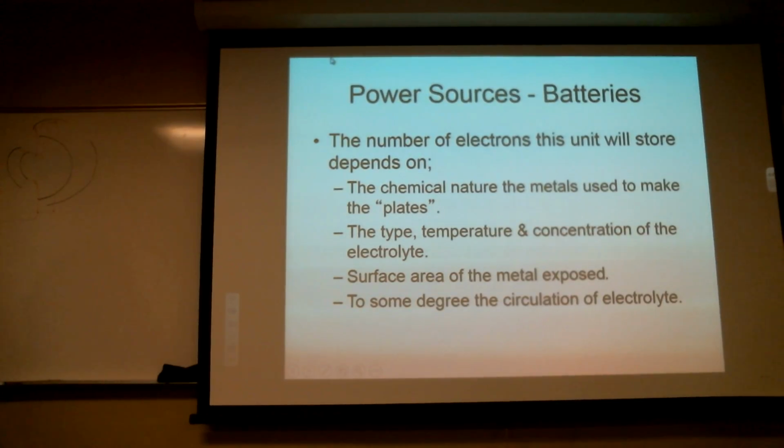Now, it's also important to note that in the world of electrical, we tend to do things in a manner of what we call preferred status. So the preferred values of voltage are 12 volts and 24 volts. Occasionally you see a 36 volt system out there, but it's pretty rare. The same thing in terms of preferred values applies to usage. For the most part, a battery is going to start an engine. Well, that's a high current draw over a fairly short period of time.